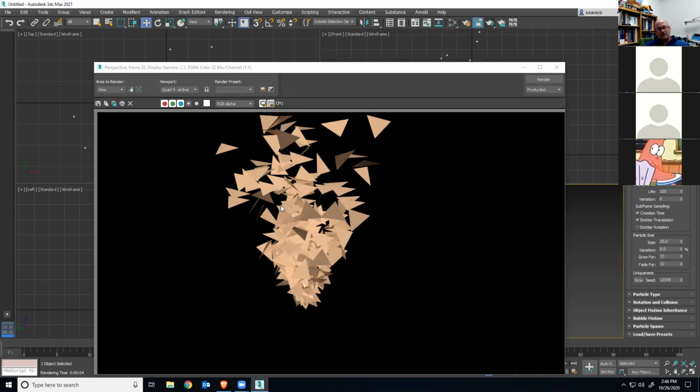So we have to consider that particle systems can generate a whole lot of geometry in very little time, right? You can crash the system pretty quickly just by typing a number, right? So there are ways to remediate the load that it puts on the computer just by changing the type of particle it is, right? So a triangle is pretty easy to render, and so it can do things pretty fast. And if they're small enough and they're going fast enough, it's tough to tell that it's a triangle instead of little particles of smoke or something.